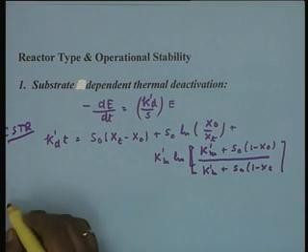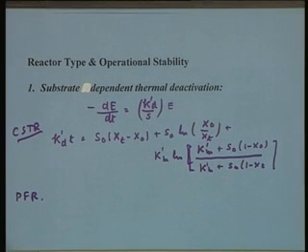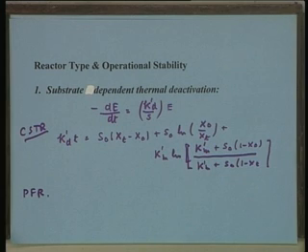Now, in the case of PFR, the situation will be much more complex, because the concentration of substrate across the reactor is not constant. So, the rate of deactivation also along the length of the reactor is different, and therefore, a simple analytical solution is difficult. One has to probably get the performance of the reactor based on operational stability by a numerical solution, and the analytical solution will be difficult,